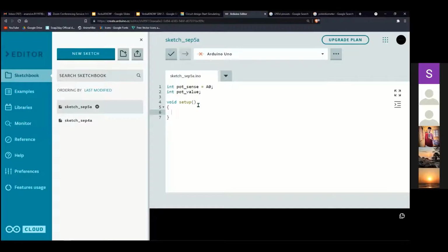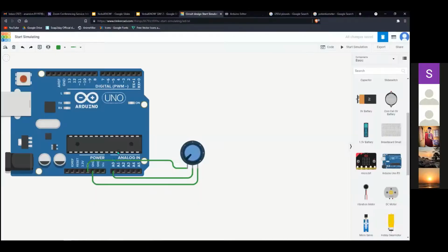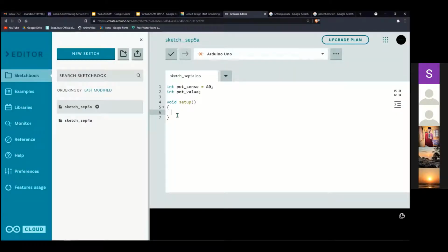One thing you need to keep in mind is that whatever the unlock signals, like the pins you are using here, A0 to A5, these pins are dedicated for the unlock function. So you don't want to mention it here in a way like pinMode, A0, INPUT. You don't require this one actually.